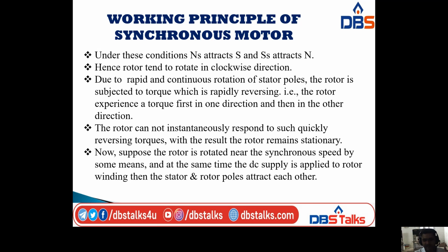But after a half period, the rotor tends to rotate in clockwise direction. So due to rapid and continuous rotation of stator poles, the rotor is subjected to torque which is rapidly reversing. That is, the rotor experiences a torque first in one direction and then in the other direction. So like that it is changing, it is reversing.